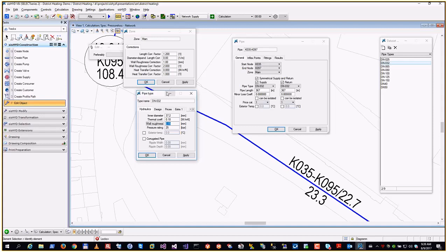The pipe vendor specifies the insulation, and I know it, for example, for ISO+, they have a catalog, and they give you a value which describes the heat loss over the pipe. And this is one of the factors that influences the temperature difference between supply and return. So when you start at the supply station with 110 Celsius degrees and you lose 3 Celsius to the end, and you operate then, let's say at 107 and 50, that makes a difference to 110 and 50.